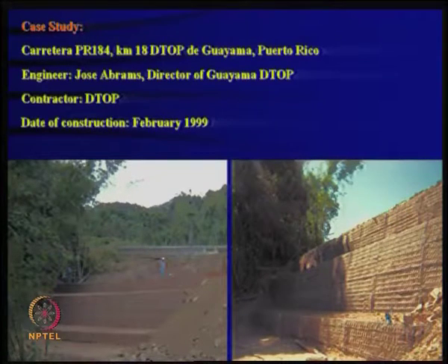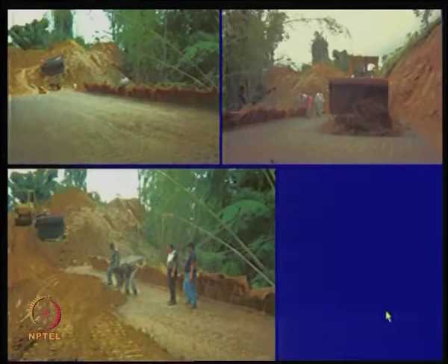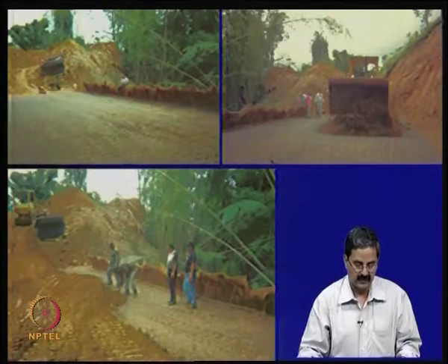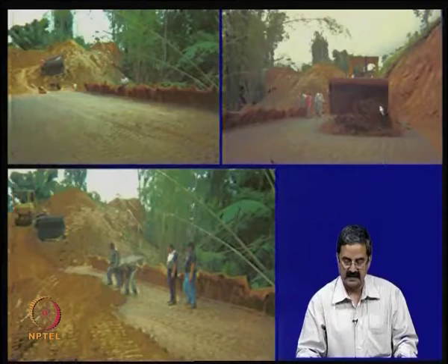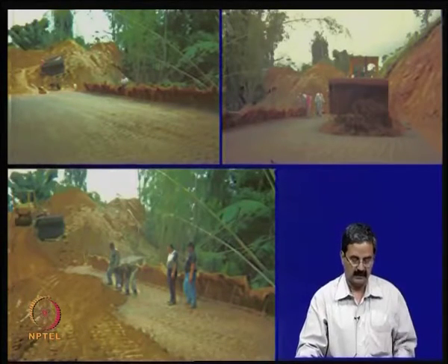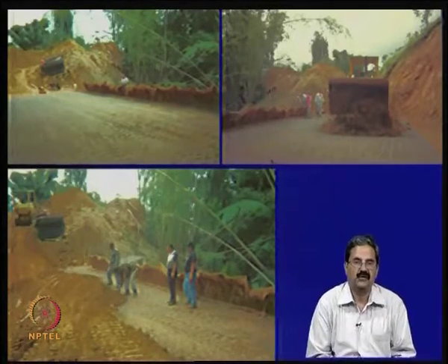And this is again, it's simple. You can see even the construction that they are doing here. Normally you have a reinforcement, and then on the reinforcement you have a backfill being spread, and then it should be rolled and compacted. As I just mentioned, it should have a good density, right?